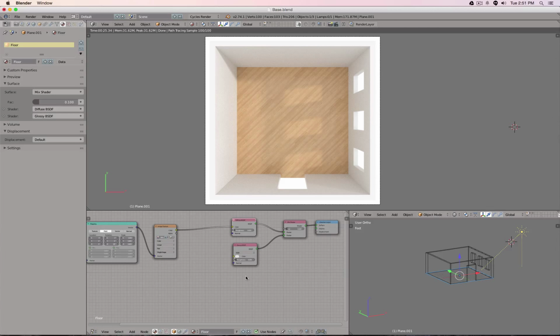Wax, you use the wax-like shader, etc. But for what we're dealing with in architecture or interior design, pretty much that's all of it. If for example something should be chrome, obviously then we can just use the glossy material and use a 0 roughness or a really small roughness, because it's not 100% polished.